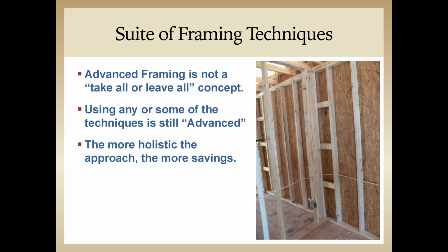So let's break down this photo. We immediately identify the ladder blocking T-intersection, which is an advanced framing technique. Looking closer, we also see raised heel energy trusses, and the OSB sheathing lapped over the trusses is part of a combined shear and uplift. However, note that the builder chose to stay with 16-inch on center 2x4 construction for the exterior walls, with random stud placement and a double top plate.